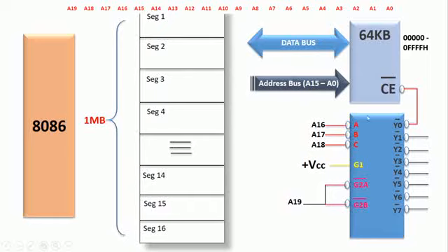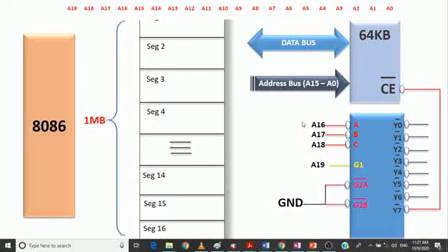Okay now, for this diagram, let us suppose I am changing the diagram. As I told you, you can choose any one of the output lines of the address decoder to enable this particular device. Now I'm changing the address line. So in this case, the output is Y3. So Y3 means the combinations are going to change. In order to choose Y3, obviously you are supposed to apply the 0 1 1 combination.